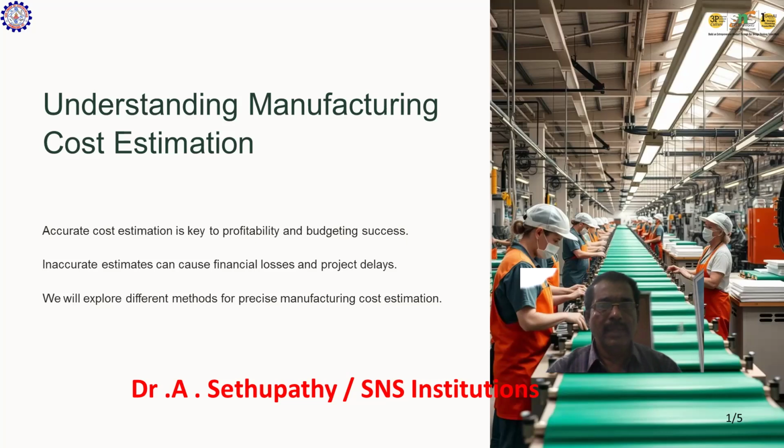So what are the manufacturing methods? The first one is the casting method, that is called molding. Molding is mostly used for producing casting parts, and casting parts are mostly used in automobile components. In molding, we have different types: green sand molding, die casting molding, shell molding, investment casting molding. Mostly we use green sand molding, as it is the cheaper one compared to other molding processes.